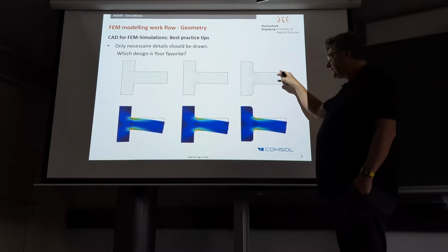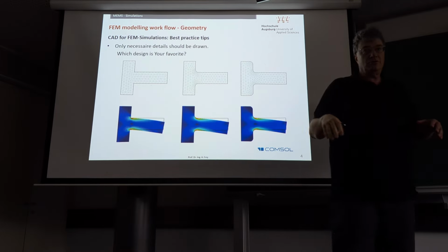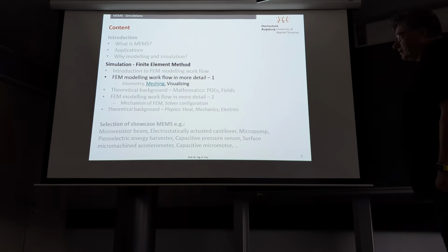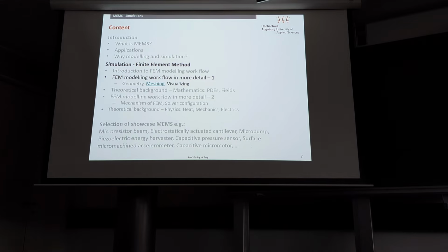Then you might remove some fillets. If you don't, then you have unnecessary mesh. That's also fine as long as you have enough memory and the CPU time does not blow up. So these are very simple examples, but they transfer to real problems in realistic situations. So that I think was important to mention again.